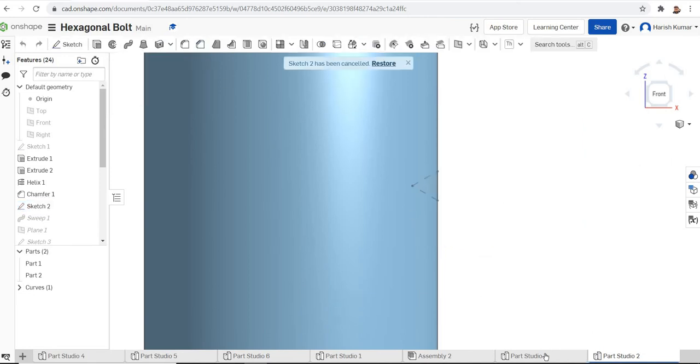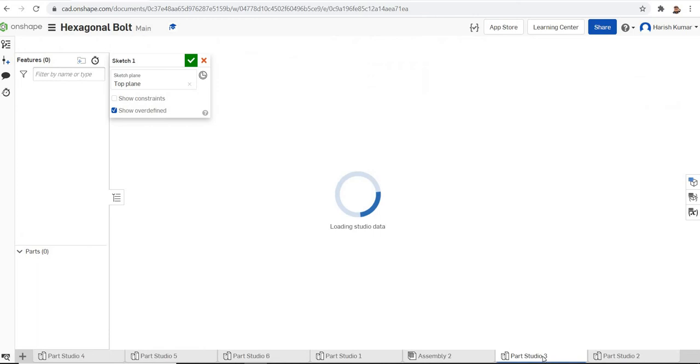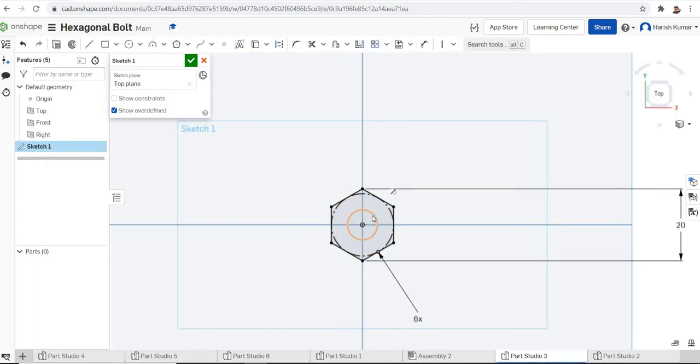our part studio. Okay, so the current part studio. Put the dimension of the hole as, so the hole major dia is 10. Okay, so 10 minus, I can put 2 into Control V. Okay, so that you can make 0.84, right, slightly less.